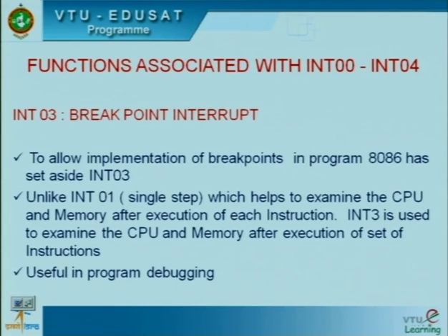Assume that you have written 3000 lines of code and there is some logical error. How do you debug that? It is better to put INT 3h after 10 or 20 lines and start executing a small portion of the code, so that you can verify the contents of the processor registers and the memory locations after executing those lines. If that is appropriate, you can remove INT 3h after the 20th line and put it after the 40th line, and so on, so that you would be able to debug the whole code.